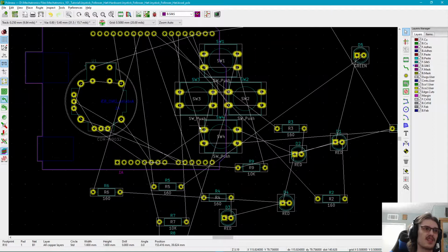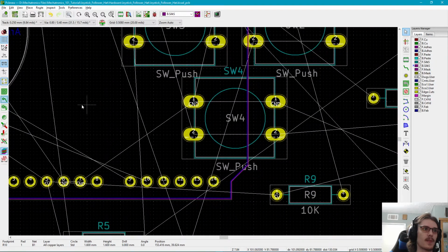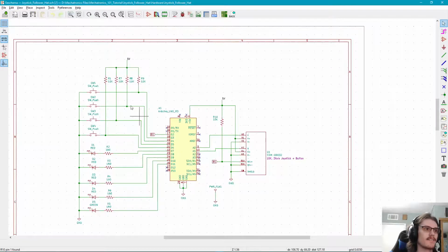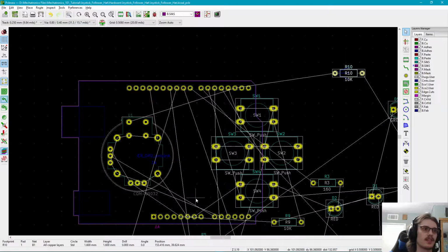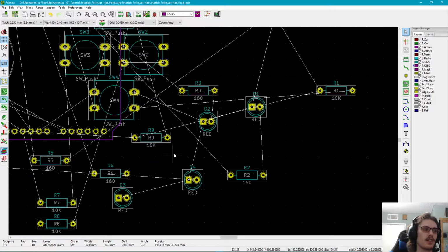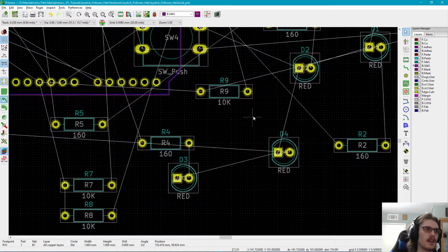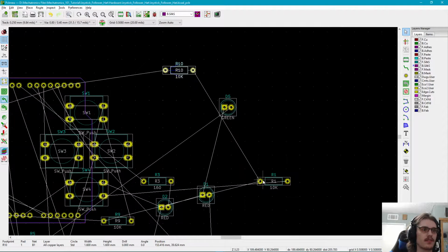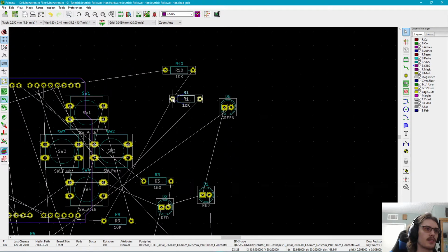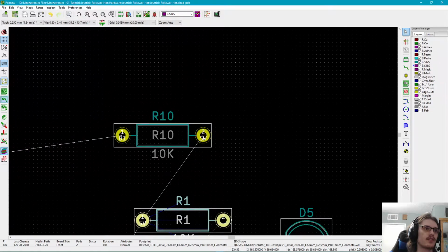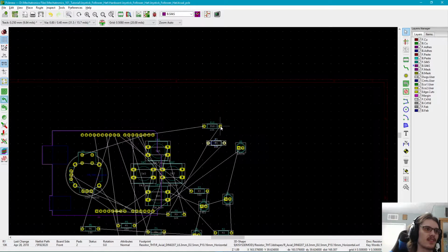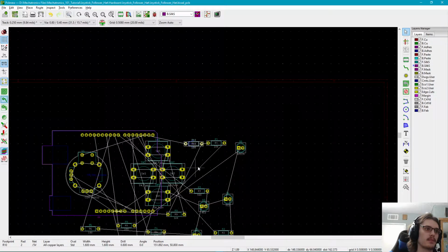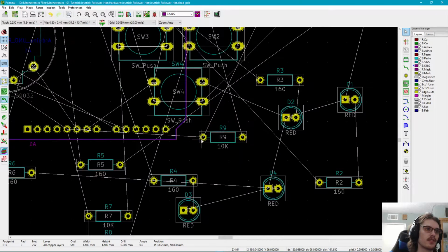What we'll instead focus on is any power pins. So if we look at the schematic, we have a 5-volt power pin, 2 of them specifically, that kind of deal with a nice chunk of everything. So let's see what stuff has a 5-volt net. You should see 5-volt wherever there is one. Here's one. R1's got 5 volts, so let's go ahead and move that close to something that's got 5 volts. I automatically know this is also 5 volts because there's this line connecting it. So these go together in a way. But they don't necessarily have to be together. See, there's another 5 volts here.